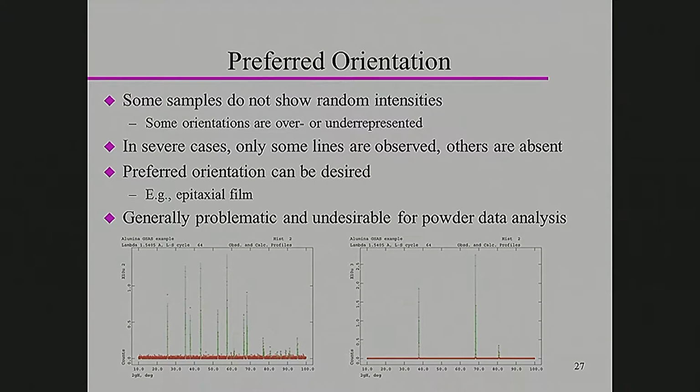How do you know whether you have preferred orientation? Good question, right? Now in this case it's extreme, easy to detect. One way to figure it out is to take one sample that you pack loosely and one sample that you really pack down, and you run the two patterns, and if the intensities look pretty comparable, your sample probably doesn't give you any preferred orientation issues. If the intensities don't look the same, there's a good chance that your sample has a tendency to orient. Okay? Make sense?